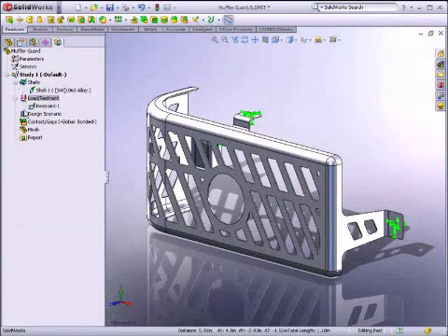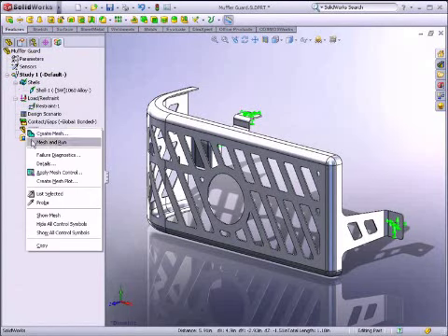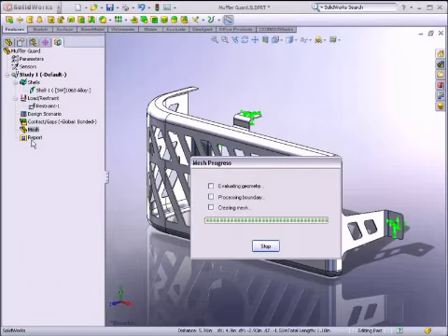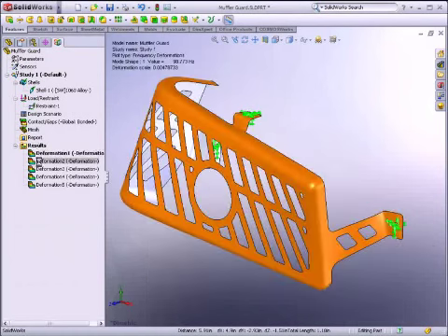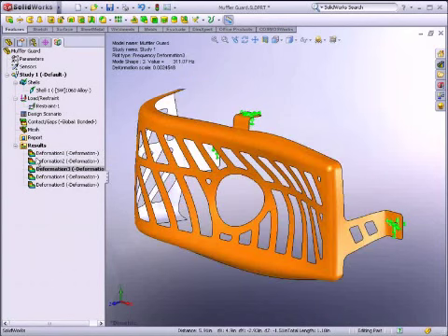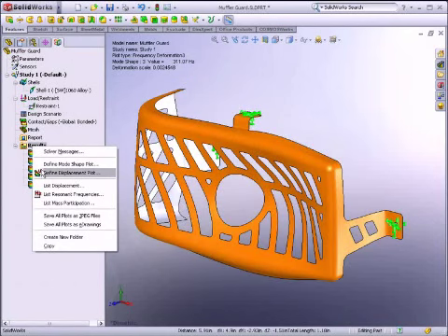Now, we get SolidWorks Simulation to apply the shell mesh. This will take less time for shell elements than it would for a solid mesh. To get an idea of how the guard deforms, we can define deformation plots at several natural frequency points.